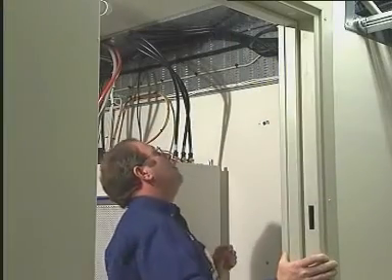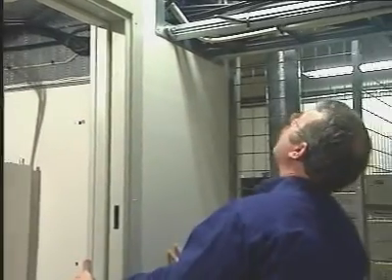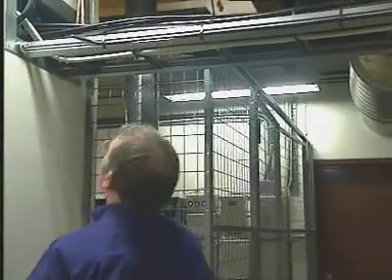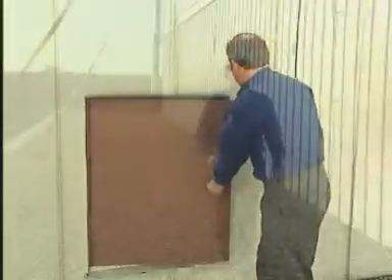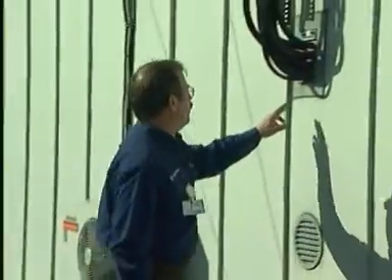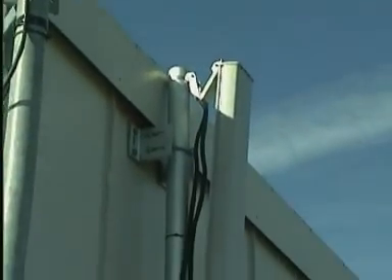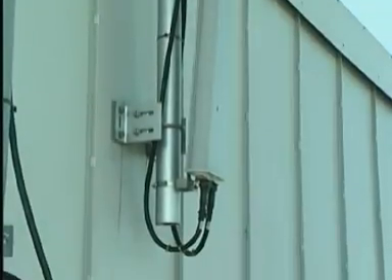Once the existence of a fault has been identified, we need to find out just where the fault lies. It is advisable to inspect the antenna system, following the feeder cables from the radio room, along the cable route, and onto the antenna. This act alone may reveal damage to cables. It will also give you a rough idea as to the approximate feeder length, although feeder length information should be available in the site documents.